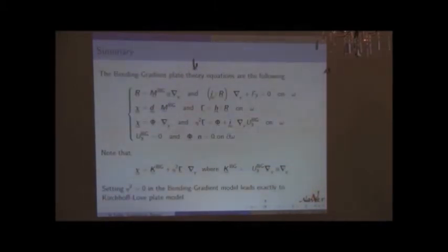So if I gather all the equations, I had the equilibrium equation we discussed earlier. I found the constitutive equations, and I have those compatibility conditions and the following clamped boundary conditions. Now you can inject the definition, you can isolate phi from the definition of the generalized shear strain and inject in the definition of the curvature.